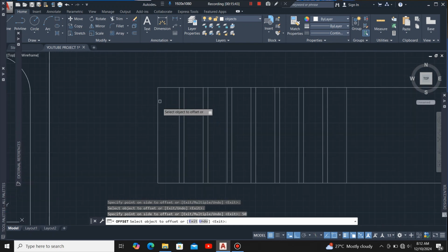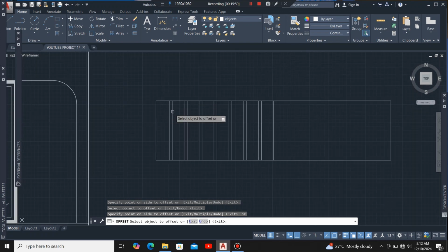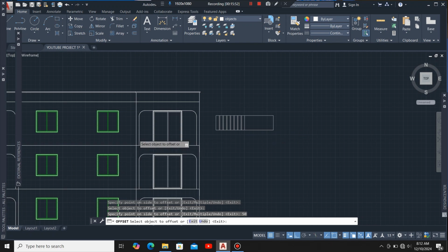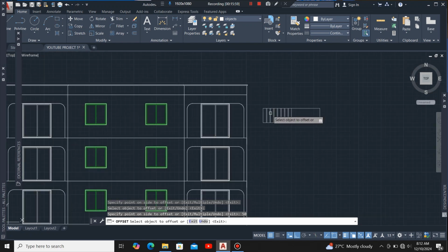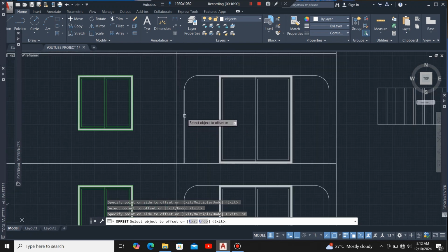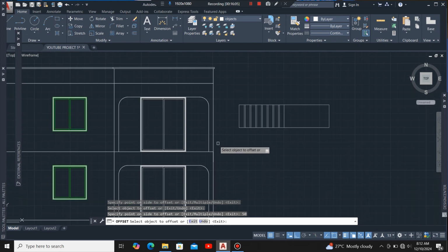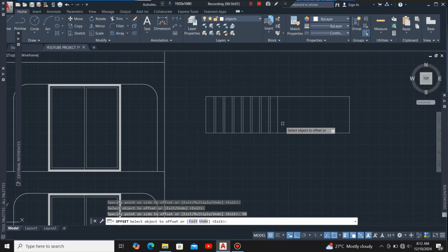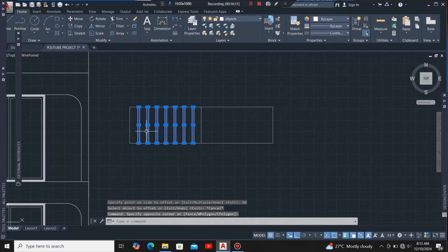Okay, I'll always leave this space such that the end parts of the guardrail that hook into the columns, this is the space that should be provided for the hooks that enter into the column, such that the guardrail can be installed firmly in this space right here. Okay, so next I'm going to highlight this.